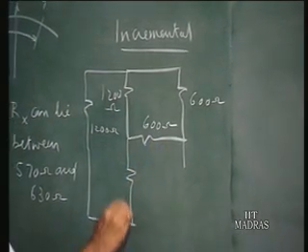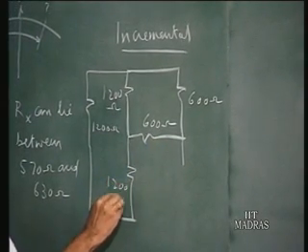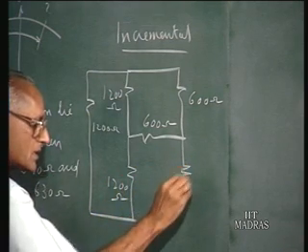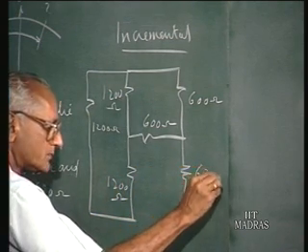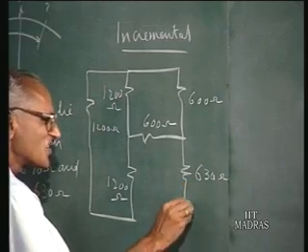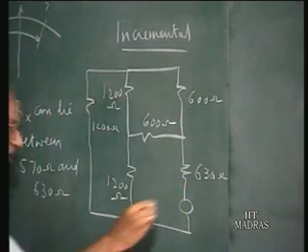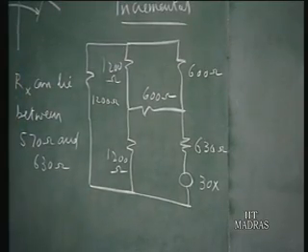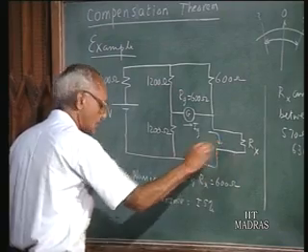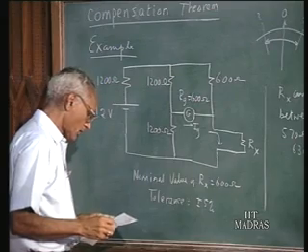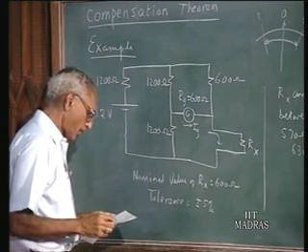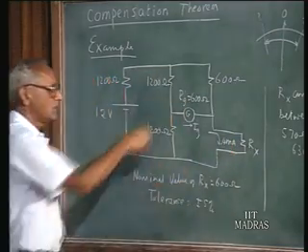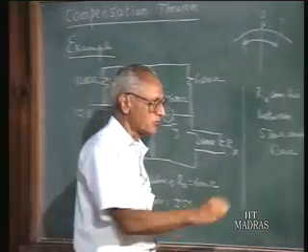And here in the galvanometer this is 1200, and in the galvanometer branch you have the altered resistance which is 630 ohms, and you have a DC source which is equal to the change in resistance, which is 30, times the original current. The original current here can be computed, and it will be equal to 4 milliamperes. So the current here is 4 milliamperes in the original network. So 30 into 4 millivolts.